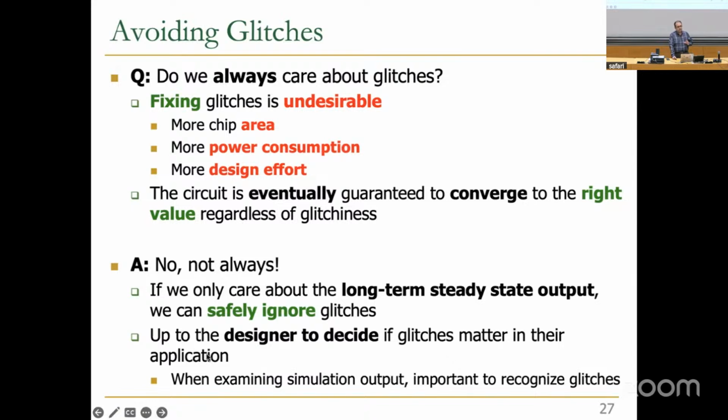Glitches can also cause unnecessary dynamic power consumption, because your output is going down and then coming up, and that consumes some power. But to avoid glitches, if you add circuits, those circuits are also going to consume power. So it may not be worth it.